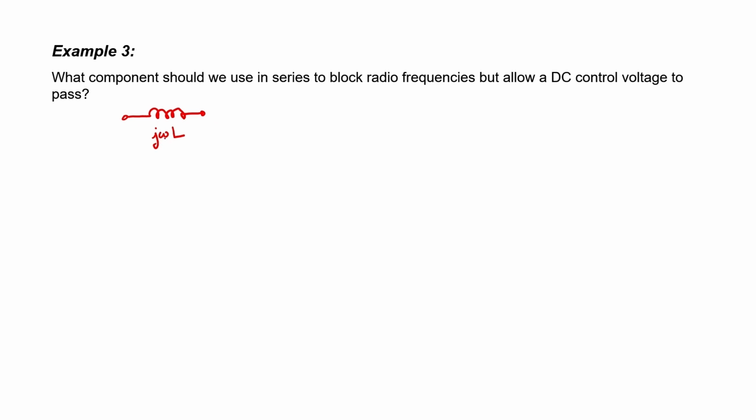However, as the frequency gets higher and higher, then the reactance of this inductor, or the impedance of the inductor, gets larger and larger, and that effectively blocks the signal. So typically inductors are used for exactly this reason. We can put it in series where any signals might pass, and the high frequencies will be blocked, the low frequencies will get through. Quite often the application is to block noise. I'll show you an example of where it's actually used.